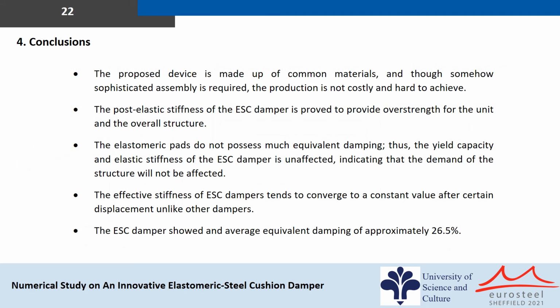The main conclusions of this study can be summarized as follows. The proposed device is made of common materials, and the production is not costly or hard to achieve. The post-elastic stiffness of the ESC damper is proved to provide overstrength of the brace and the overall structure.